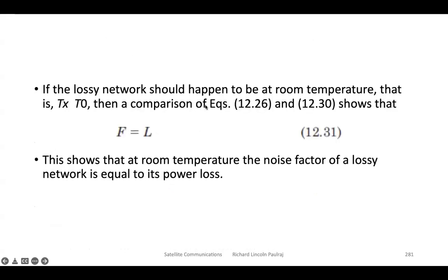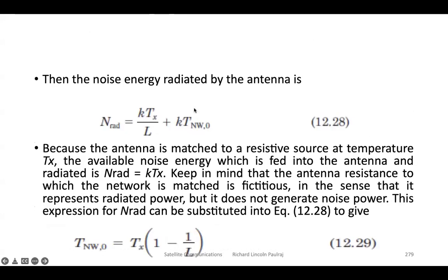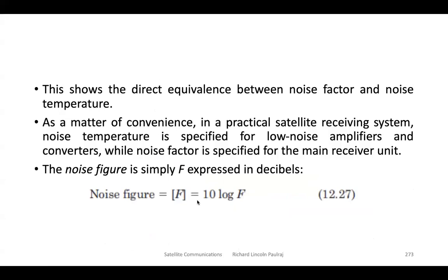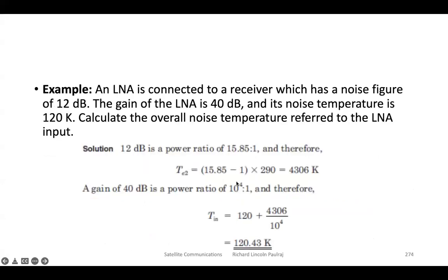Moving on, remember I had told you about noise figure and noise factor. I hope you all remember that. For noise figure, we use this kind of nomenclature, and noise figure is going to be 10 log of F. So what is F here? It's the noise factor.